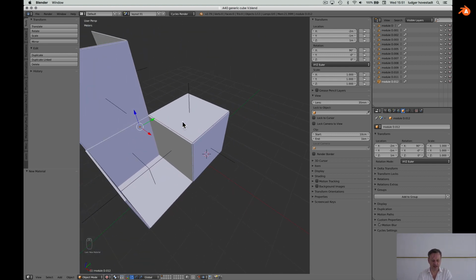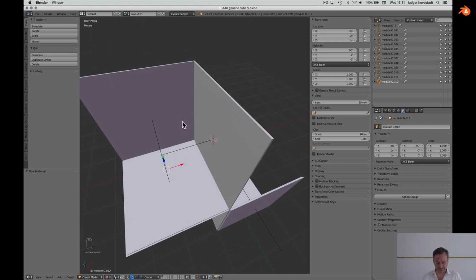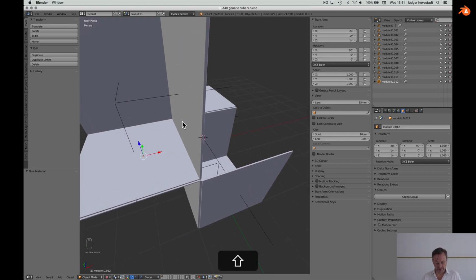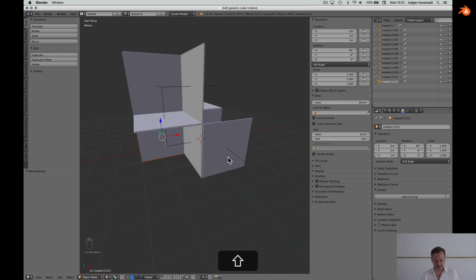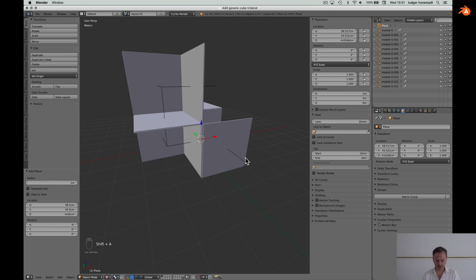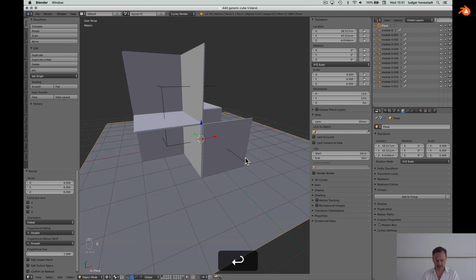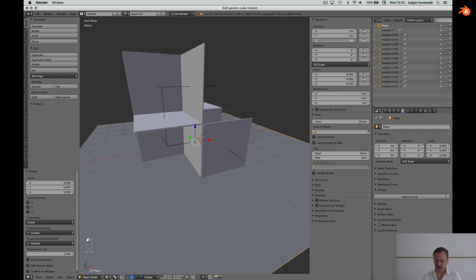Good. If you want to render that, we choose another layer for the sun. You go here and the plane. So go for stage. Scale by 6, and we have 1 centimeter down, so put this here first to 0, that's fine, and then minus 2 centimeters, so then we have the lower edge.